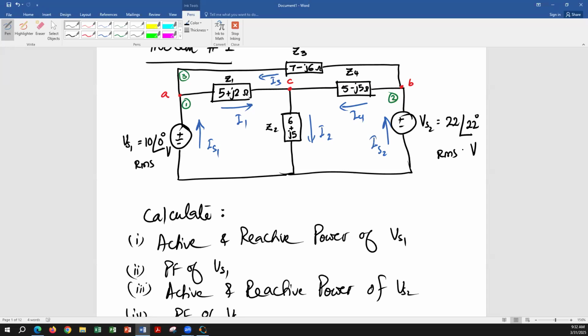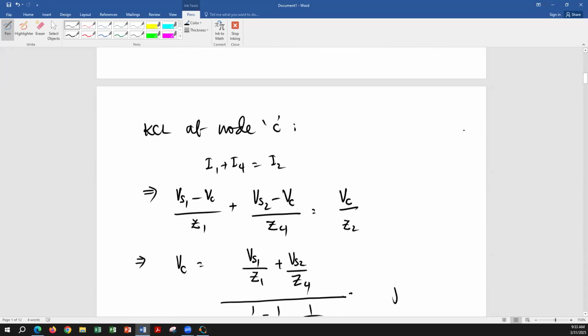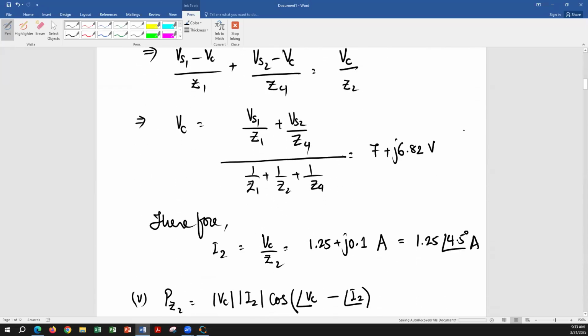But if it is given in phasor domain, then sometimes you can give an RMS value or you can give a peak value. Mostly you give peak value. But if in some book they say take it as RMS, then take the magnitude as RMS. So in this case, let's assume we are taking RMS. So 10 is RMS. Peak will be 10 times the square root of 2. If it is not being told, assume every time it's peak and then calculate RMS. In time domain, it's always peak, remember, because the time domain signal is going to be 10 cosine omega t plus theta, right? So the 10, of course, represents the peak value of the cosine, always.